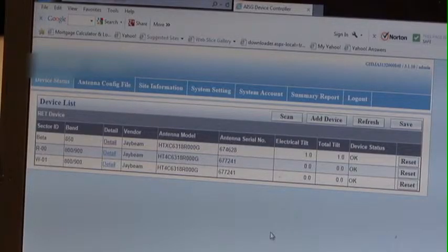Using the SCU system. For RET or TMA device status, all the RET and TMA devices at the base station site that can be controlled remotely are listed on the device status panel. RET antenna down tilt and or the TMA mode and TMA gain can be adjusted remotely through the detail panel.